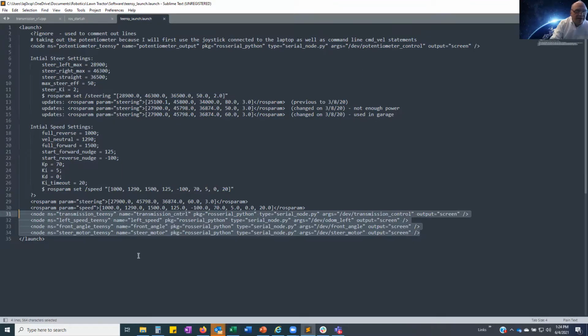Because I wanted to use USB, and I didn't want everything run through one. I wanted to separate things out and have small things instead of one big, large thing. There are actually several things there. Number one, if you've got several small processors, you've got the code for just that one device running on it, so you don't have to mix the code. You don't have the code for all 4 of those things running on the same processor, so it's easier to keep track of.